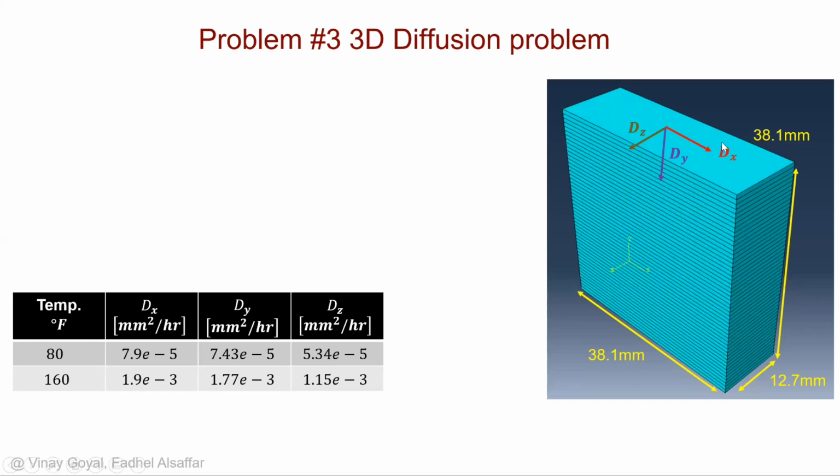We modeled the material as an orthotropic material. We added that, and we saw how we set the material orientation as well. Then we applied the same boundary conditions, same everything, and saw how the material property changes along Y, Z, and X. What you can do later is actually to mesh the whole material along X, Y and Z and apply diffusion from different directions and see how that happens.